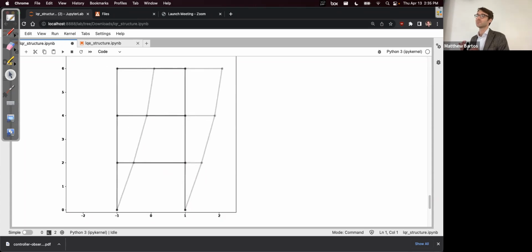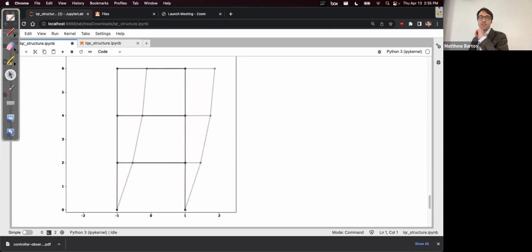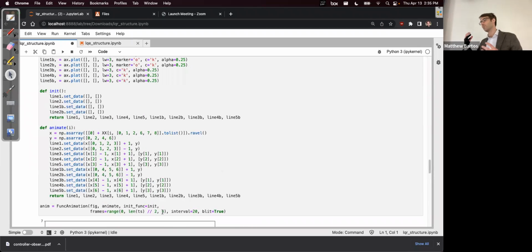Yeah, so when you're defining the Q and R, does the magnitude of the cost make any difference, or is it only the relative? The relative magnitude is what's going to affect the control strategy. But when you go to optimize the function, the final value of your optimized function will be different depending on what Q or R is.